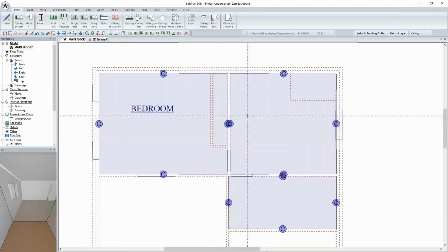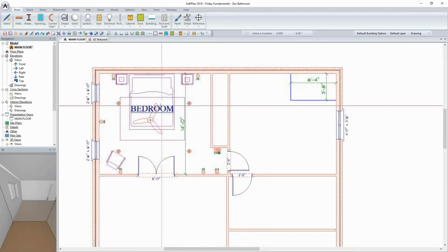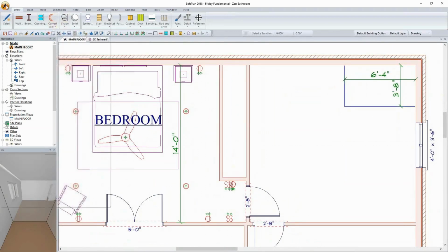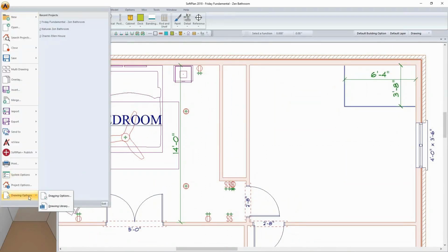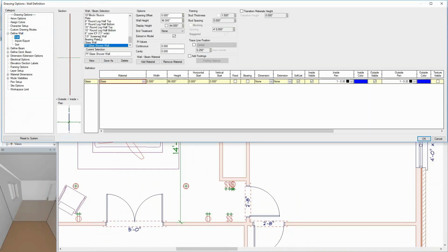Another thing that I may do is create some sort of a curb that's going to be in there, because we're going to place a curb around where the bamboo planter is going to be. And so if I come in, I could actually do the same thing just by coming in through File and the drawing options. And once again, inside the define wall, I'll do my edit, and this is where I can now come in and create another new wall, and this is just going to be a curb.